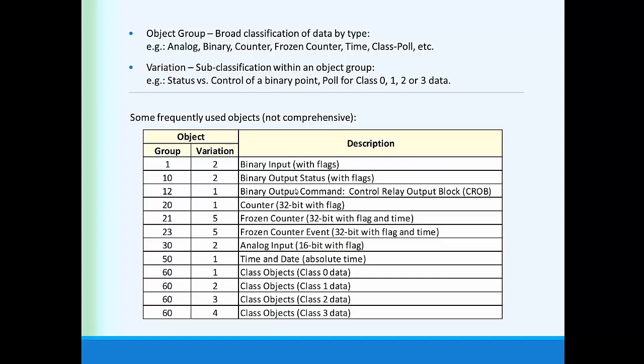It monotonically increments. It never goes up and down like amps do. And analogs, which do go up and down like volts and amps, would be the way that an RTU could ask for just amps, volts, watts, and vars. Give me object 30, and that would give me all of the analog values available from a panel instrument. Or object 20, give me all the counters from a billing meter. From a relay, give me all your binaries.